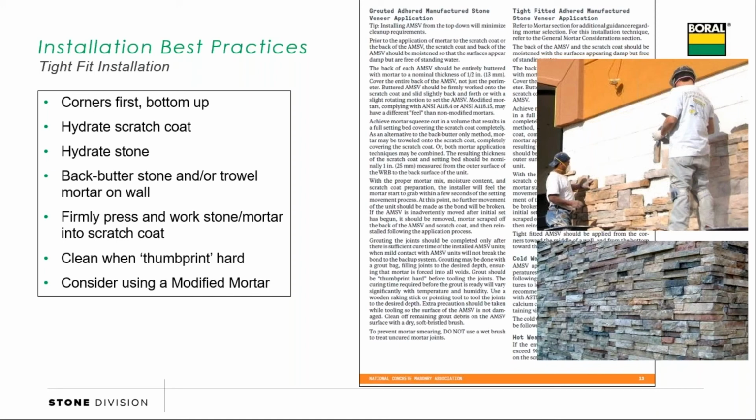let it rest for 2 or 3, get that false set or first set, depending on what you call it, splash of water, and then agitate for another 3 or 4 minutes. That's for your conventional type S or N mortars. That makes sure that that Portland cement gets fully hydrated, and to make sure that that Portland cement can make the chemical and mechanical bond it's intended to make.